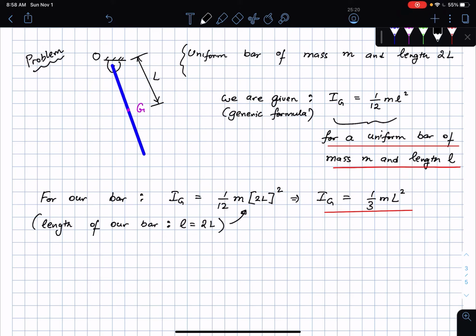All right, now this bar, as you know very well, is rotating as a rigid body. It is going to have a single degree of freedom, which I'm going to call theta. We'll do a more elaborate analysis on the number of degrees of freedom later. For the time being, you know that this is a planar motion. If I locate the center of mass, that's good enough in terms of configuration coordinates, and then I can say that the number of degrees of freedom is only 1.